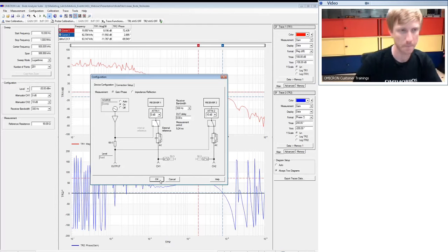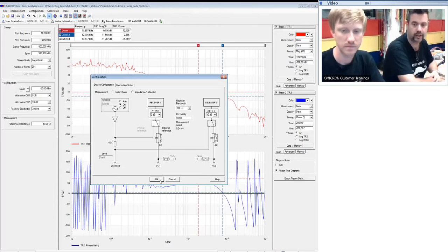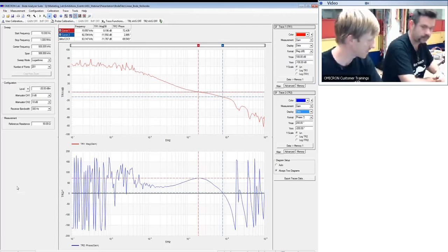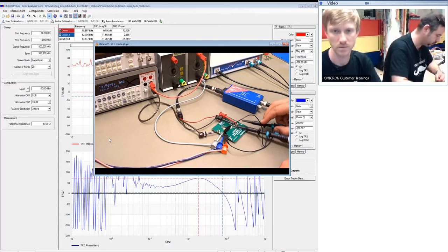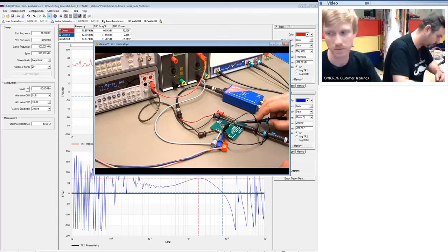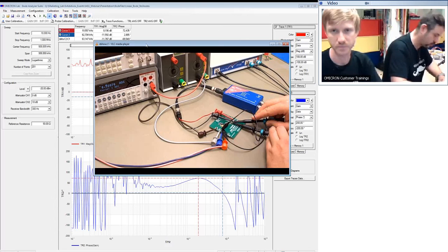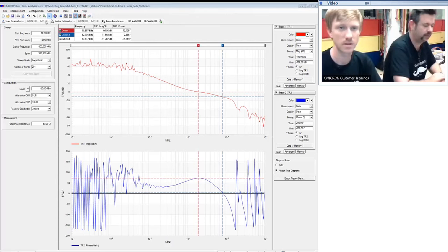And in addition, make sure that the 50 ohm resistors are switched off. So this will ensure that you can use standard oscilloscope probes, either 1-to-1 or 10-to-1 for your measurement. Bernhard, let's check if the probes are compensated correctly. Okay, can we do that now, I think? For sure. I will just now connect both probes to the same point, and if everything's fine, we should get a flat line for both the phase and the gain. Now start the sweep.